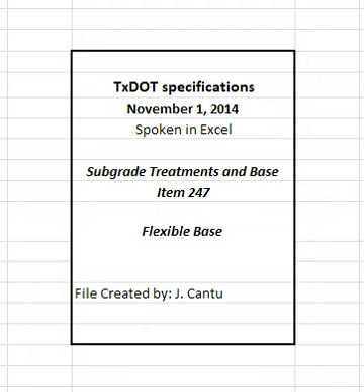5.1 Cubic yard in vehicle. By the cubic yard in vehicles of uniform capacity at the point of delivery. 5.2 Cubic yard in stockpile. By the cubic yard in the final stockpile position by the method of average end areas. 5.3 Cubic yard in final position. By the cubic yard in the completed and accepted final position.